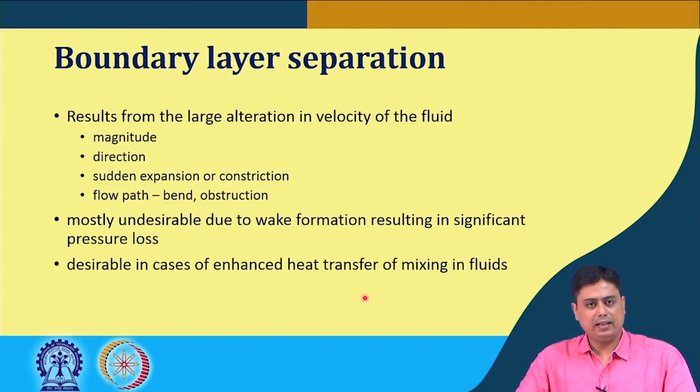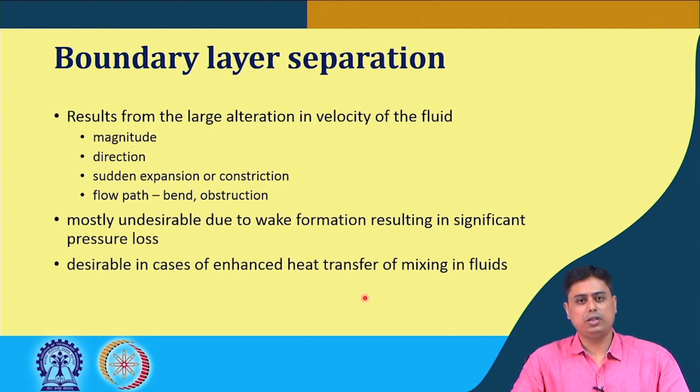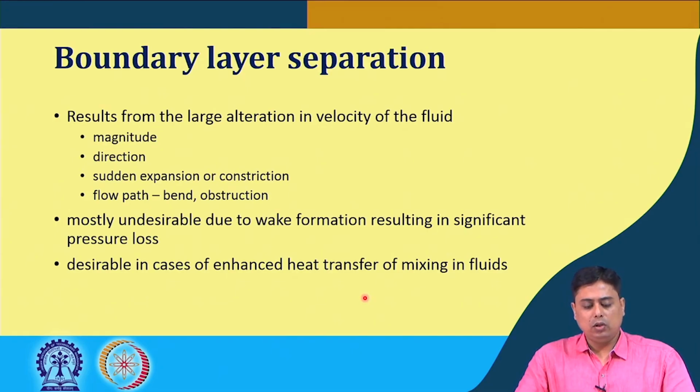So, boundary layer separation is mostly undesirable due to the wake formation that results in significant pressure loss, but it is sometimes desirable in cases where we require enhanced mass transfer or mixing of fluid. In those cases, this kind of wake formation or local turbulence is helpful and helps us to have the enhanced conditions.